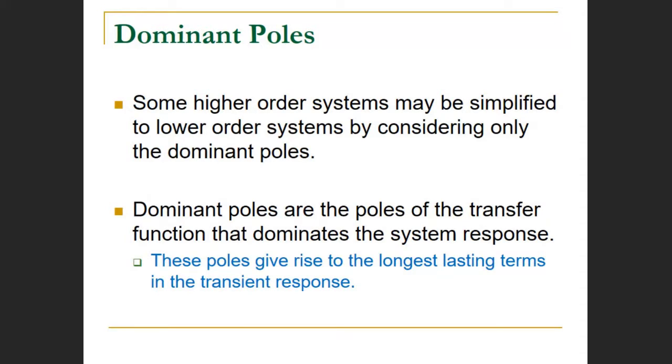It's not difficult for us to analyze first order and second order systems, and we have not looked at the analysis of third order systems. But beyond second order, it becomes more difficult to analyze. So the argument I'm presenting is that when we consider dominant poles, we're talking about poles that dominate the behavior of a system.